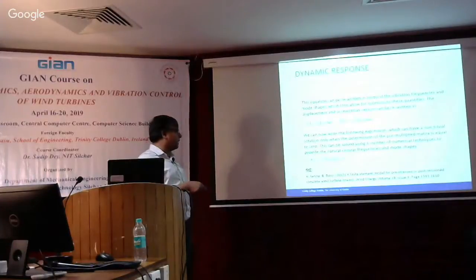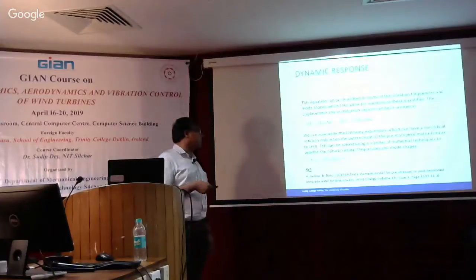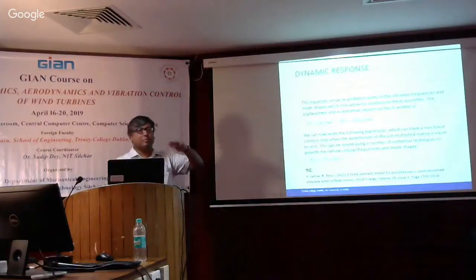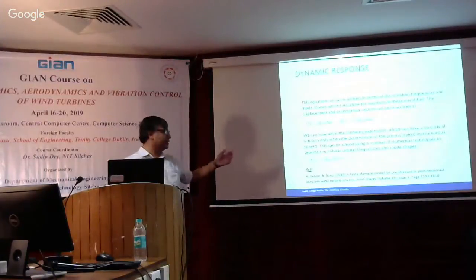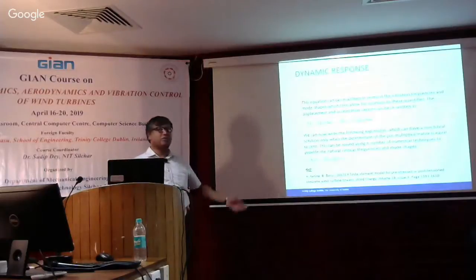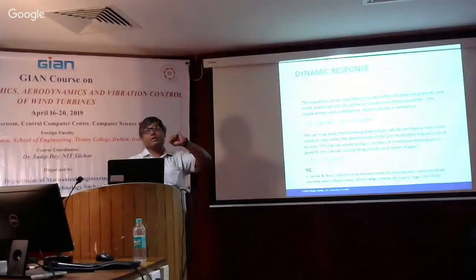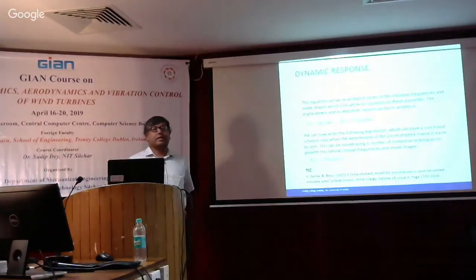This is a paper in wind energy again, where we developed a finite element model of a pre-stressed or post-tension concrete wind tower. We've done work with the hybrid tower as well, so it's partly steel, partly concrete. But here we are using the shell. This will give you some idea about how to use the intermediate reinforcing bars, or stiffening elements, and how to consider those, or if you have to look at thermal effects or long-term effects in terms of strain, relaxations, and so on. All those things are there as well.